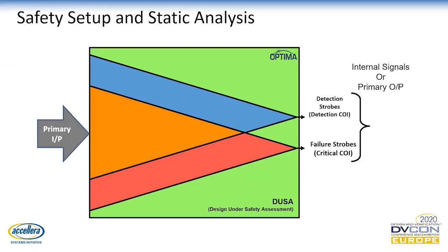So there is an intersection between the detection scope and the failure scope, right? Let's see how the faults fall into different areas and how we segregate them. The user or the designer should focus more on this area, because these faults are unsafe. Unsafe because they are ending up at the failure scope, and invisible because they're not ending up at the detection scope. So these are the faults which don't have any safety mechanism. That's why we call this unsafe, invisible. And the designer has to make sure that there is a safety mechanism present to take care of the faults which occur in this area.